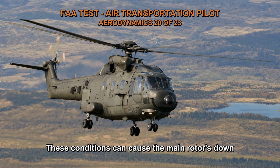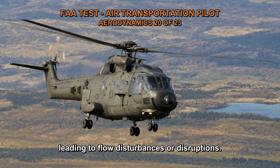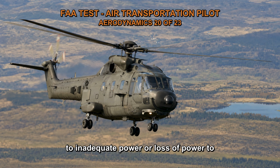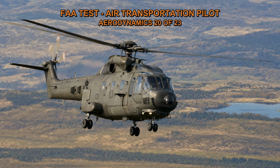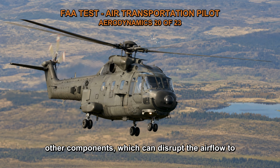These conditions can cause the main rotor's downwash airflow to interact with the tail rotor, leading to flow disturbances or disruptions. Some factors that can contribute to the alteration of airflow through the tail rotor and result in LTE include ineffective tail rotor thrust due to inadequate power or loss of power to the tail rotor, disturbed or turbulent airflow from the main rotor, which can occur during high power demands or aggressive maneuvers, aerodynamic interference from the fuselage, vertical stabilizer, or other components, which can disrupt the airflow to the tail rotor.